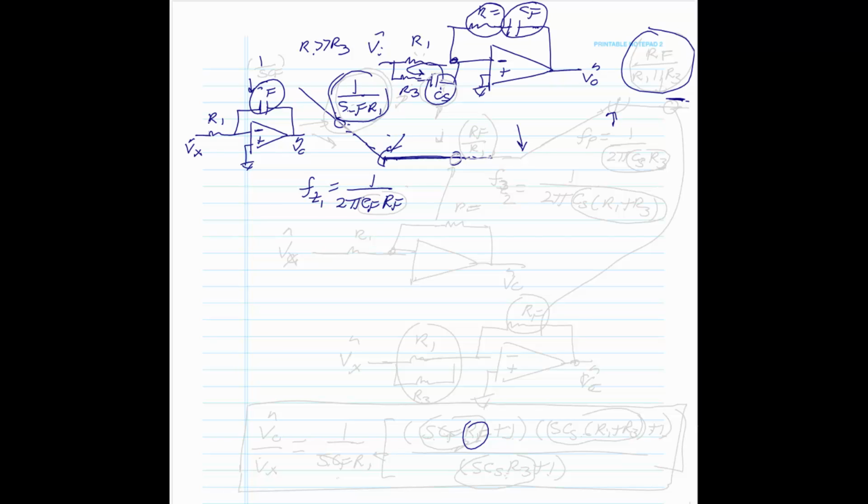It's 1 over sC, so 1 over sCF divided by this becomes 1 over s CF R1. That's this circuit right here. What does the circuit look like here? As we said, the capacitor now is lower than RF, so RF dominates. It's a series circuit, and we have a circuit that looks like this, because CS did not come in yet.